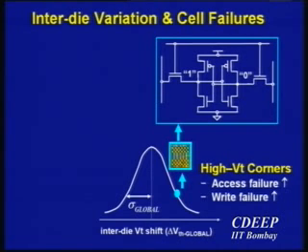So we didn't put in any redundancy, no row redundancy, no column redundancy, no ECC. And it turns out, just because of these variations, and in that case, we looked at about 40 millivolts variation in the threshold voltage, the yield of that memory, and of course, it didn't have redundancy, it didn't have ECC, the yield was about 45%.